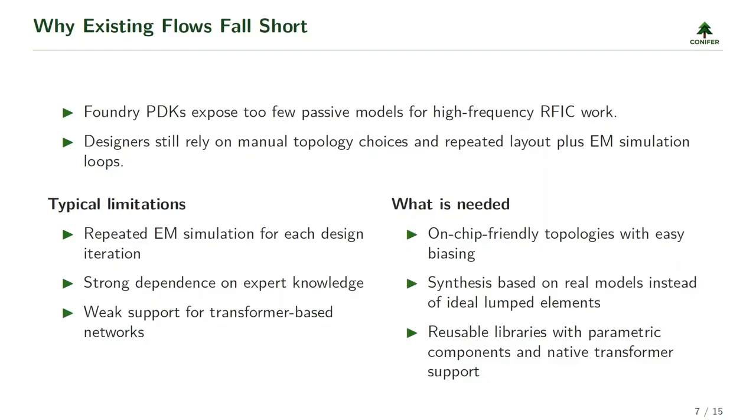As electromagnetic simulation has to be repeated for each design iteration, this iteration time represents a significant chunk of total design time, which is a serious limitation of the existing flows. Another limitation is that the design result is strongly dependent on the designer's expertise. Also, at very high frequencies, the best performance can be achieved by transformer-based matching networks. But for this matching network type, there is only weak support by existing tools.